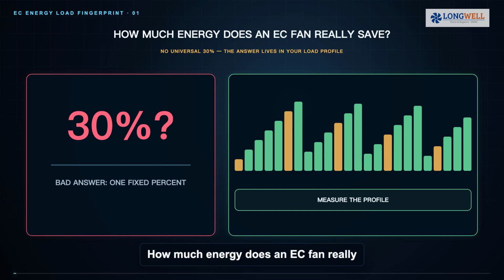How much energy does an EC fan really save? The honest answer is not a universal 30%. Savings depend on what the fan delivers, how many hours it spends at each load, and exactly where electrical input is measured. We need the annual load fingerprint, not a badge.